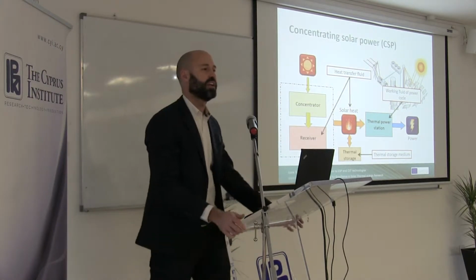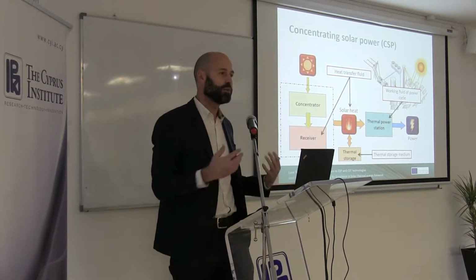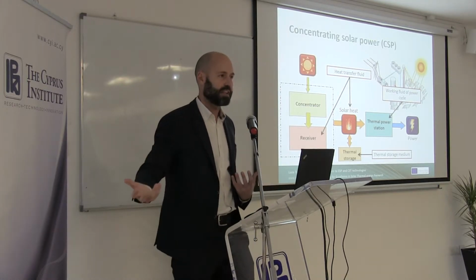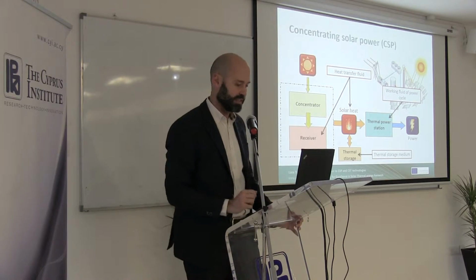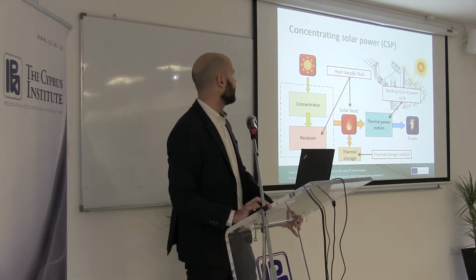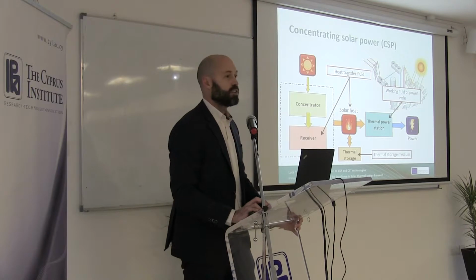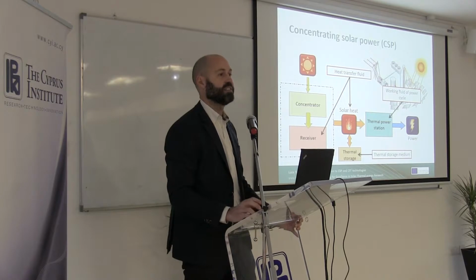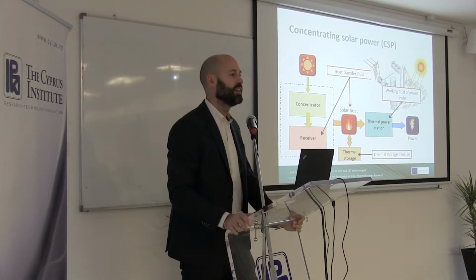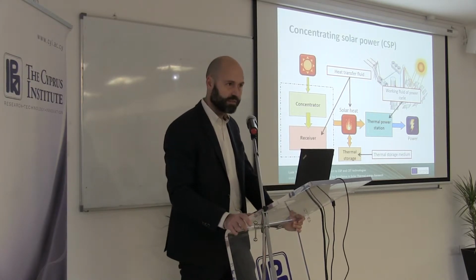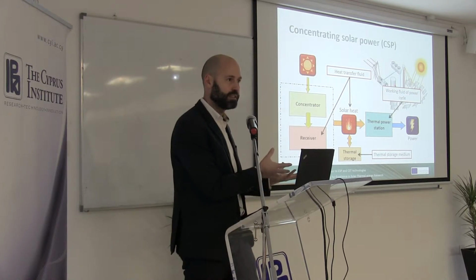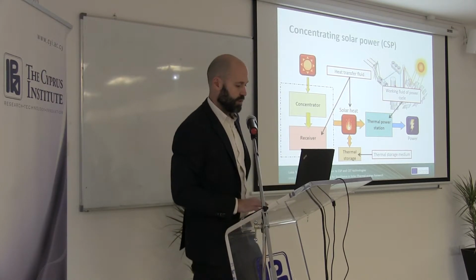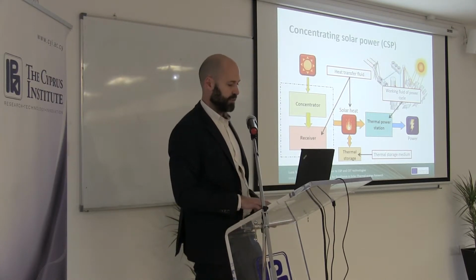You will see this especially in the dish lecture, where you will use air as heat transfer fluid in the receiver, and this air is the working fluid of the thermodynamic cycle used to convert heat into electricity, for instance. You may have the same fluid for collecting heat in the solar field and storing energy, as in so-called direct thermal storage systems, where you heat up a fluid and you store this fluid to store the energy collected, and so on. So these fluids may be different.